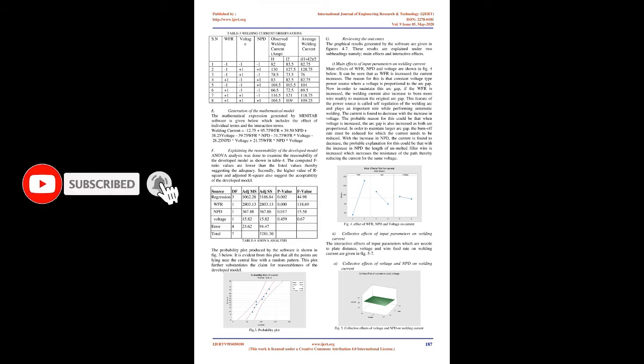E. Generation of the mathematical model. The mathematical expression generated by Minitab software is given below, which includes the effect of individual terms and the interaction terms. Welding current equals -12.75 plus 95.75 WFR plus 39.50 NPD plus 38.25 voltage, 39.75 WFR*NPD, 31.75 WFR*voltage, 28.25 NPD*voltage plus 21.75 WFR*NPD*voltage. F. Explaining the reasonability of the developed model.